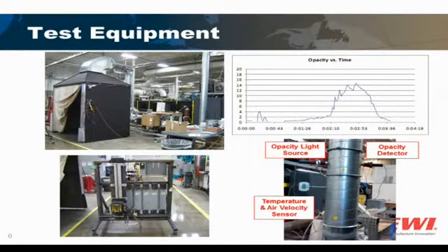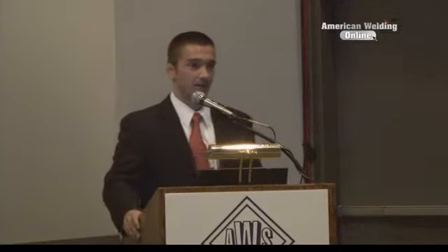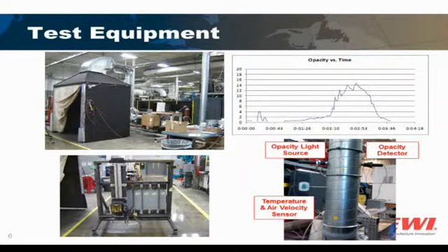So opacity is not something that's normally measured in a laboratory type environment. So we had to design a system for comparing opacities produced through different trials. So what we did here is we designed this cutting system that consisted of a fume hood, and then the fume was pulled through the ductwork, which was pulled by a blower fan. And that had a variable speed damper on it so that we could set the flow rate constant.